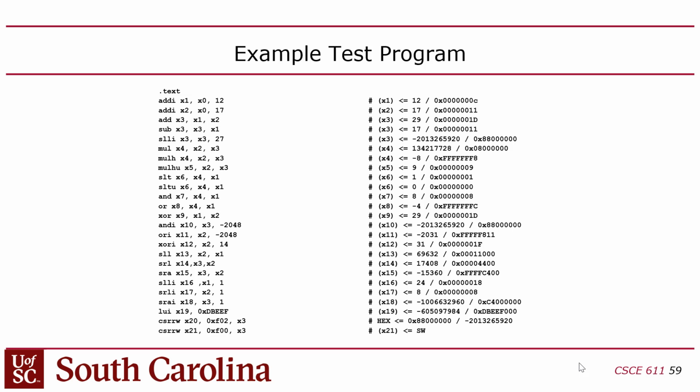Right? Now you might say, what about the hex displays? Why not just have it write the hex displays at the end? And if it writes that, the test bench will see the hex displays being updated. Yes, that's correct, but that's only the last. In order for that to happen, every single instruction would have to execute perfectly. What we really want is to be able to test each individual instruction in a self-checking test bench, and there's no way to do that. The only thing we thought of is you could expose the register file write data and write address ports to the outside world, like make them ports. Then you could use that.